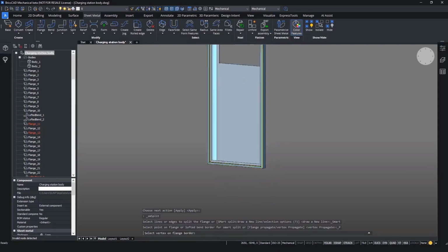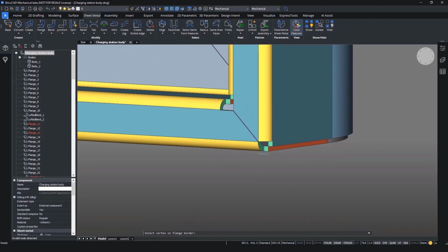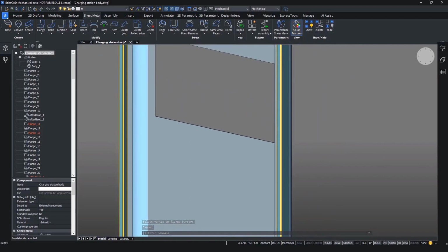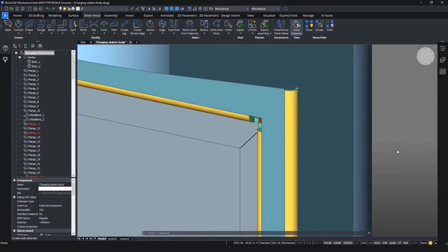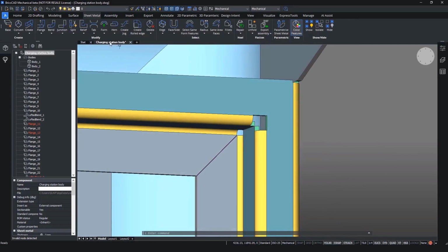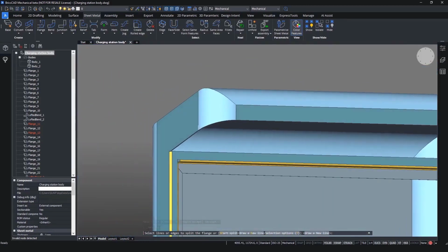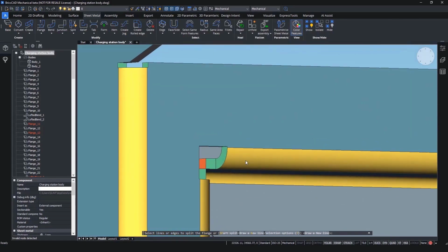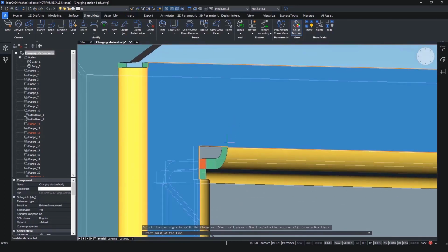But we can also split this design into several members so that it can be cut out in separate parts and later added together. Here on the upper part of the door, there is some geometry that we need to solve. Currently, it cannot be unfolded with the rest of the door, as it would overlap and collision between these flanges would occur. So like I mentioned earlier, this indeed cannot be manufactured as it is, no matter how much information we apply. However, there are some occasions where it could work, but the unfolding would not be ideal in terms of saving material or saving space.